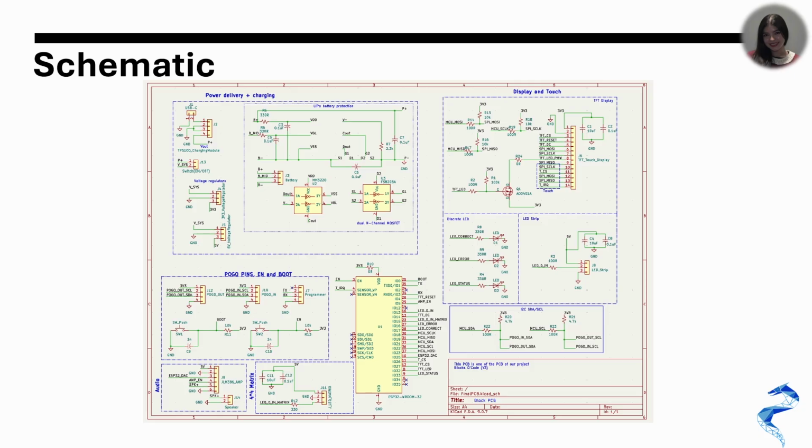Since the battery voltage varies, we regulate it before powering the system. A 5-volt regulator supplies higher power components like the LED strip and amplifier, while a 3.3-volt regulator powers the ESP32 and other logic components. Capacitors are placed near the regulators for filtering and stability.